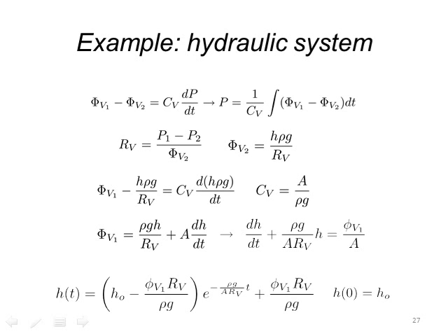So we can use these components as lumped elements if things are flowing in the right way, and if we can assume laminar flow inside these little tubes, then we can do quite a nice little job of modeling these hydraulic systems using the same lumped modeling techniques that we've seen throughout the course.